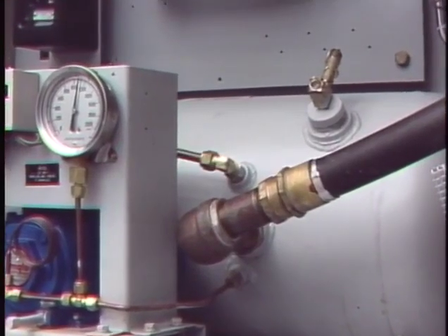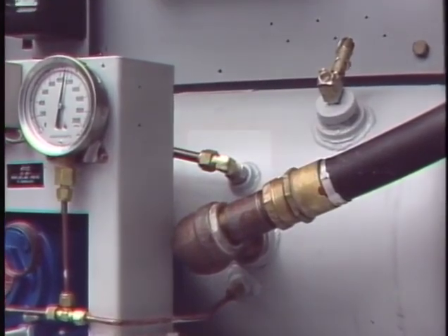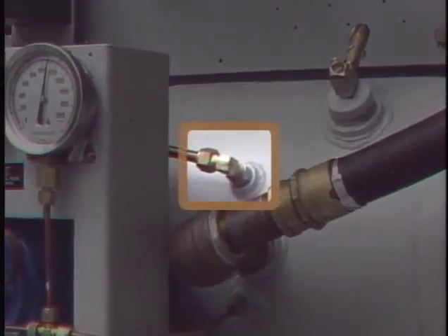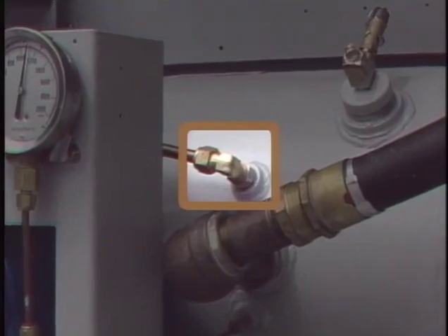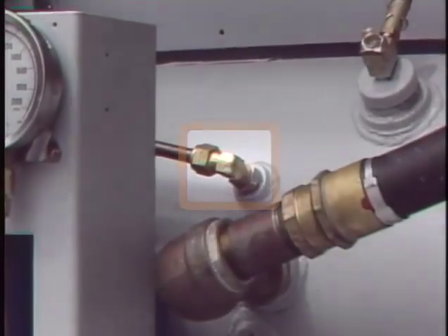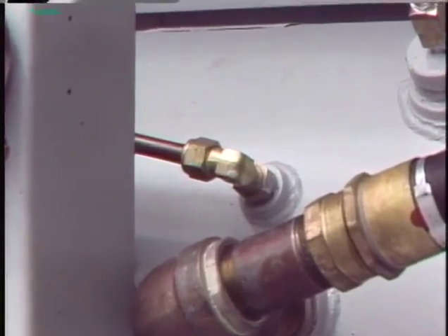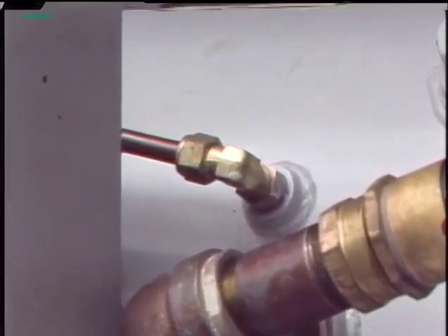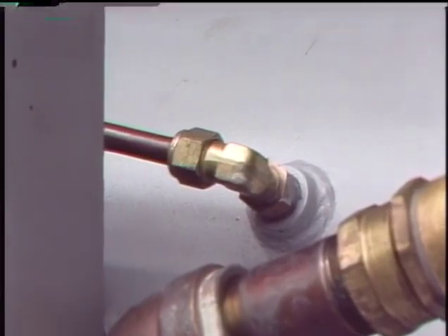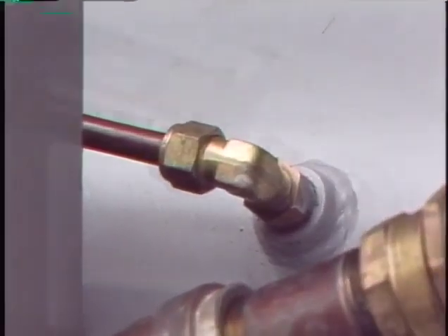If a leak isn't found using the solution, the loss of pressure may be caused by a bad check valve in the supply line from the compressor to the storage tank. The valve allows air to be pumped into the tank, but it normally prevents air from flowing back out. A bad valve may allow air to leak out of the tank into the supply line.